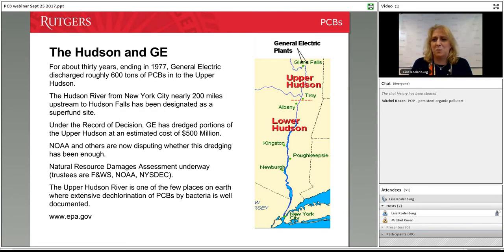What often happens in these kinds of dredging operations is that the dredging material comes up like what they call black mayonnaise. It's real runny, and it's very difficult to do anything with it because it just runs through your fingers. So what they do is they add cement to it to tighten it up and make it more solid so that they can actually work with it.